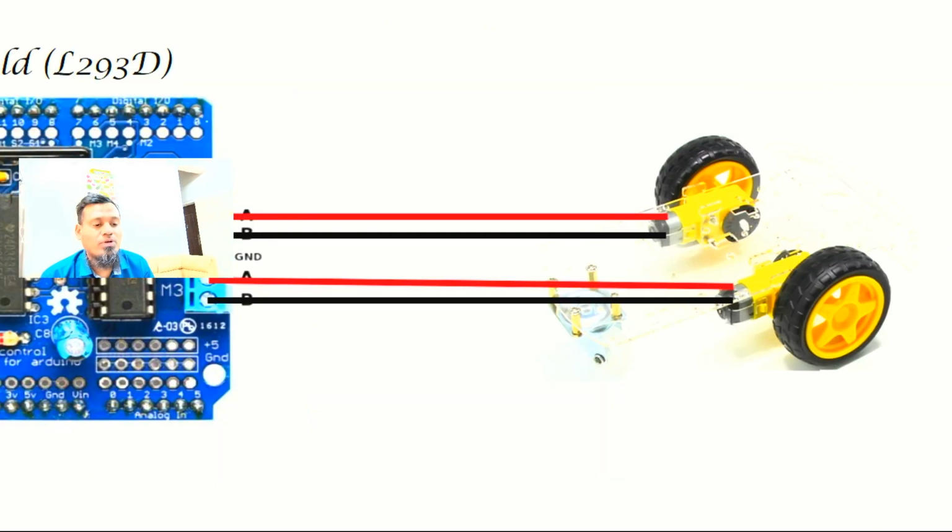In the front side you can have this caster wheel. No need to connect a drive wheel here. You can have this caster wheel in the front side, so that it will decide its rotation depending upon the drive wheel's rotation. Or if you intend, you can have two caster wheels in both corners, or two free wheels without any motor, same like this wheel, in the front side without any drive motors, which can rotate freely with the direction decided by the drive wheels.